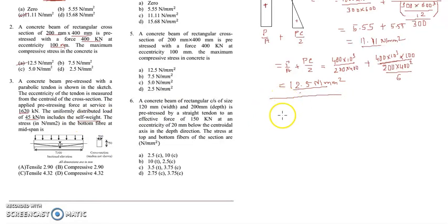So for the final one, they are asking at the bottom fiber. I know there's going to be a direct stress P by A, and because this has an eccentricity, this is where I need to calculate the stress. So at that point, the eccentricity is e mid.